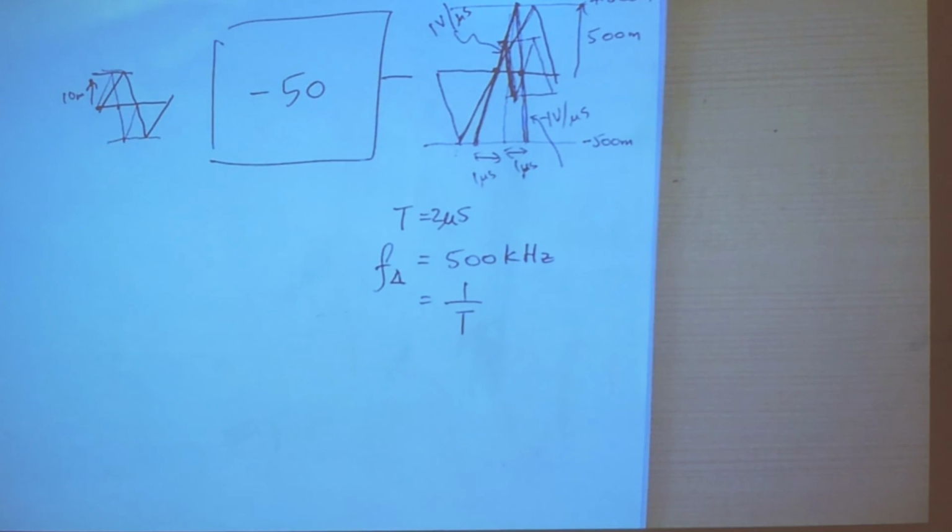You are not getting the same gain anymore. You're not going to get 500 millivolt anymore. Alright? Because of this slew rate limitation. Any question?